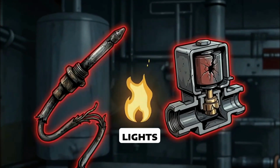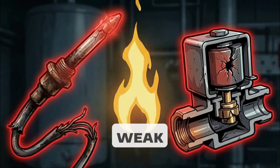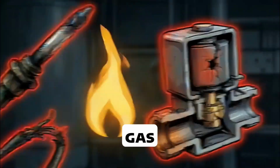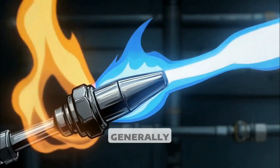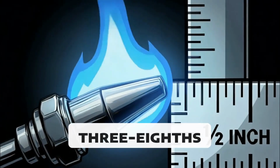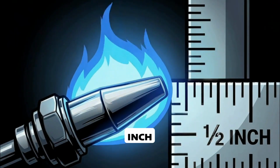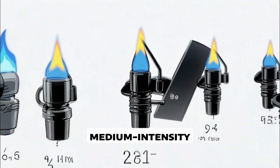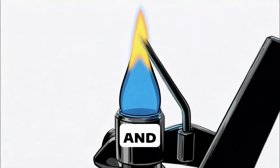If a pilot lights but will not stay on, suspect a weak thermocouple, poor pilot flame, or faulty magnet in the gas valve. Pilot flame should generally engulf only the top 3/8 inch to 1/2 inch of the thermocouple tip. A proper pilot flame is medium intensity blue with minimal yellow tips and no soot.